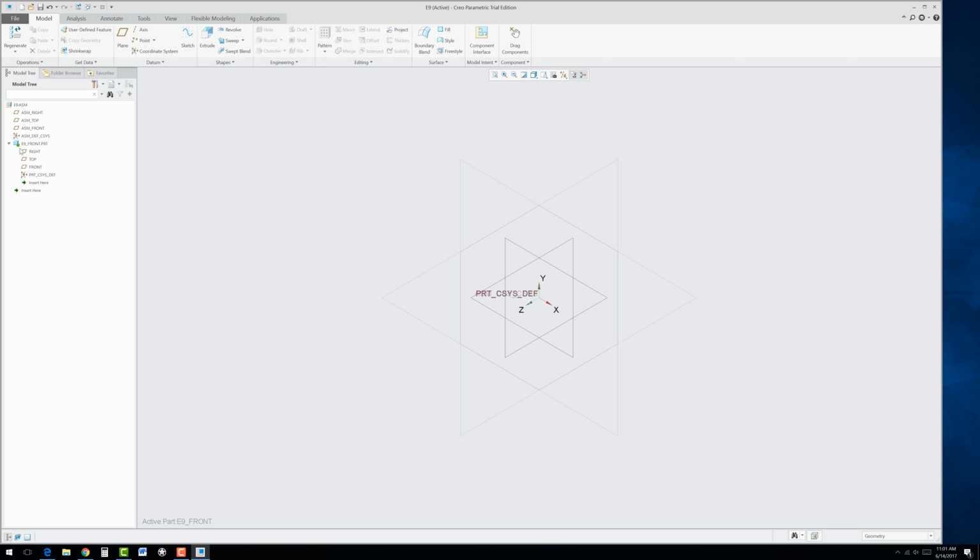So anyhow, another little side note is when you're going to start a sketch, I have students ask, should I sketch on the front plane of the assembly or the front plane of the part? You could, but I would recommend sticking with the part file as best as you can. Remember, you could sketch off of any model that's in there, as long as it's flat, any surface of a model, and sometimes you could use that to your advantage. In this case, just to keep those links to a minimum, we're going to try and maintain most of what we have here in this part.